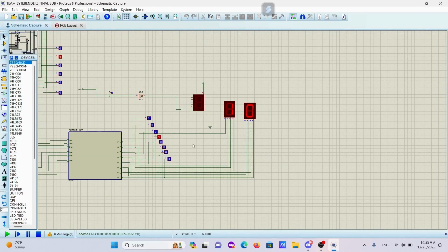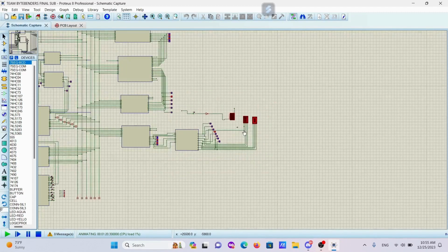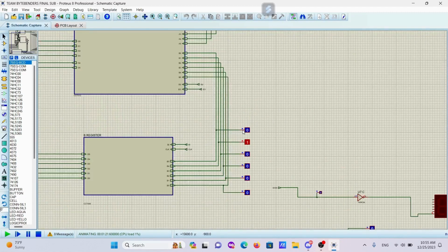Here the delay is occurring due to the clock circuit, because in the clock circuit, if we change the resistor and capacitor values, then the delay can be minimized. Also there are many NOT gates which are making the delay, I guess. So it can be changed. Now here we can see that at the B register, 2 is loaded, which was the second number.